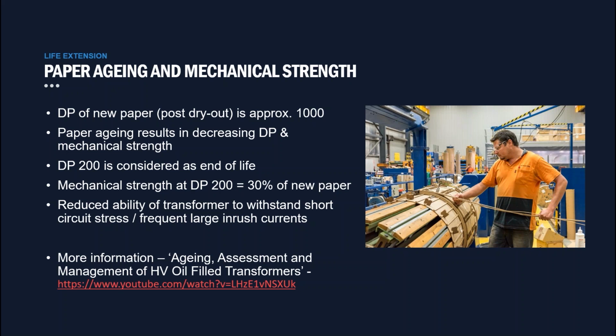During operation, a transformer can be exposed to high levels of moisture, like the previous transformer. So this can degrade the paper. We'll see this degradation by reductions in the degree of polymerization, and a DP of 200 is theoretical end of life. And there's more information about DP, end of life, increased failure risk, and mechanisms of failure in a technical presentation we recorded last year. This can be accessed by this link on the bottom of the page, and you'll get a copy of this presentation.